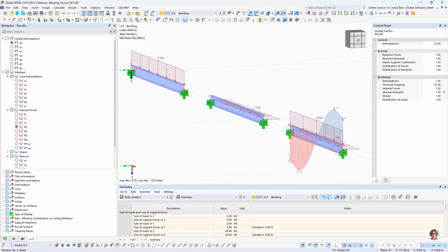We now see that in the double bending case, not only My and Mz are present, where by the way the weak axis bending moment has now increased by almost a quarter with respect to the reference configuration. But now we actually also have a torsional moment, and because we don't have a uniform or a constant torsional load along the beam, we should also have a share in secondary torsional moment, and this would give us also some warping moment over the member length.